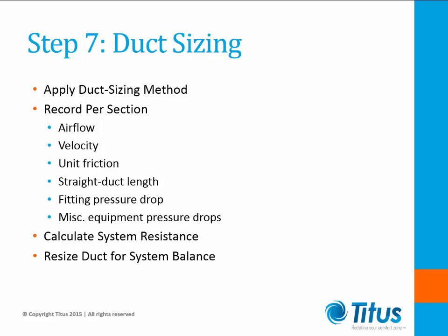For single duct VAV systems, dual duct, and parallel fan powered terminal units, calculate pressure drop all the way through the diffusers. For a series fan powered box, provide minimum pressure across the unit air valve for design airflows, as the terminal unit will provide pressure for the secondary distribution through the diffusers and grills.